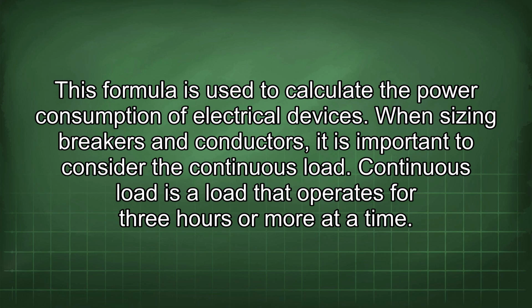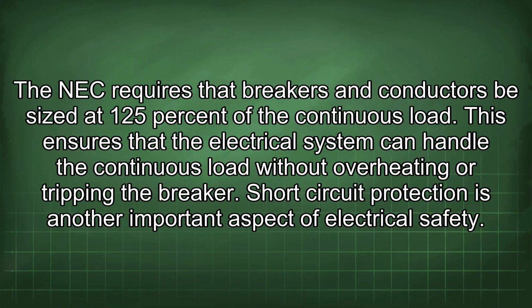When sizing breakers and conductors, it is important to consider the continuous load. Continuous load is a load that operates for 3 hours or more at a time. The NEC requires that breakers and conductors be sized at 125% of the continuous load. This ensures that the electrical system can handle the continuous load without overheating or tripping the breaker.